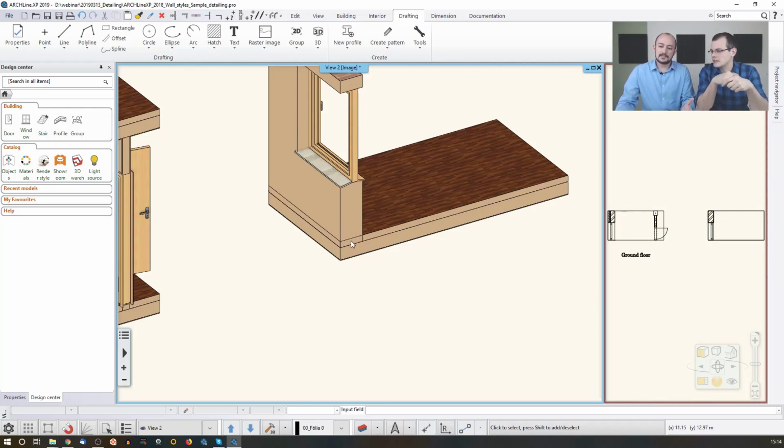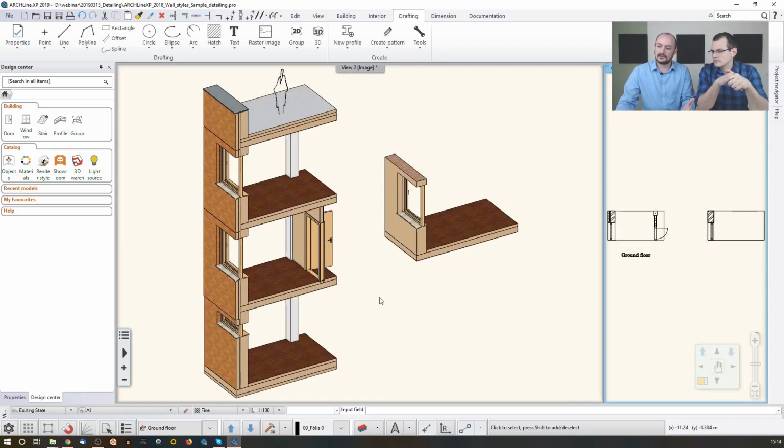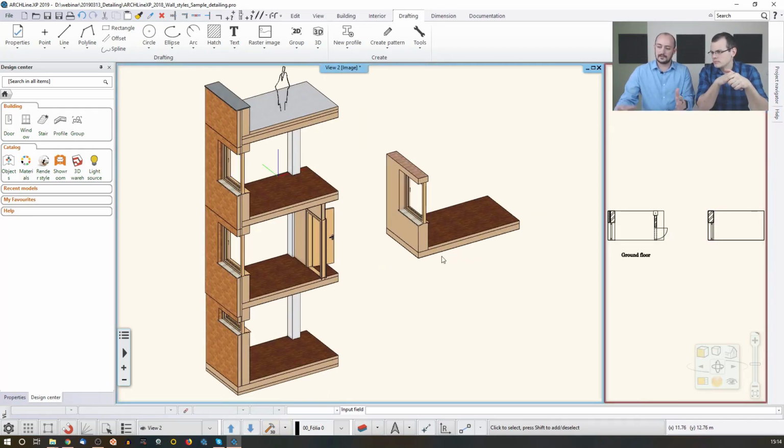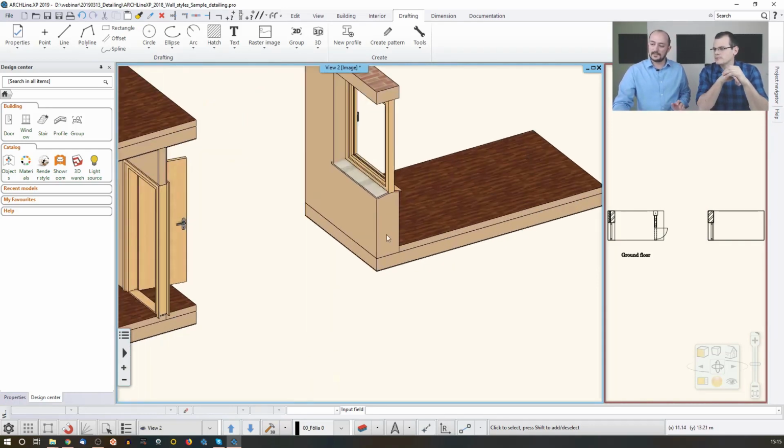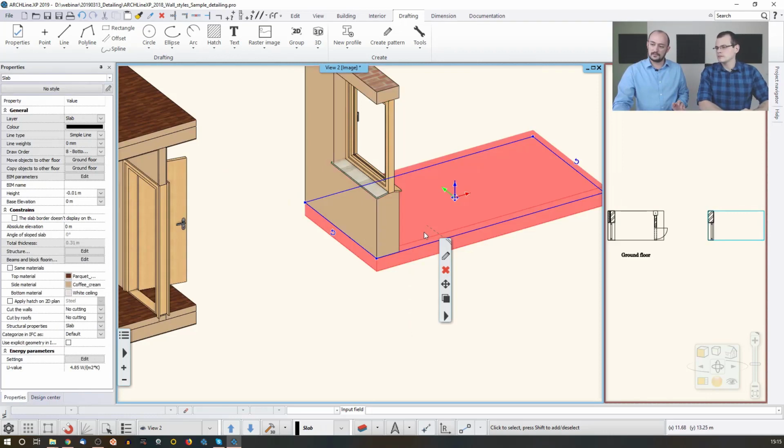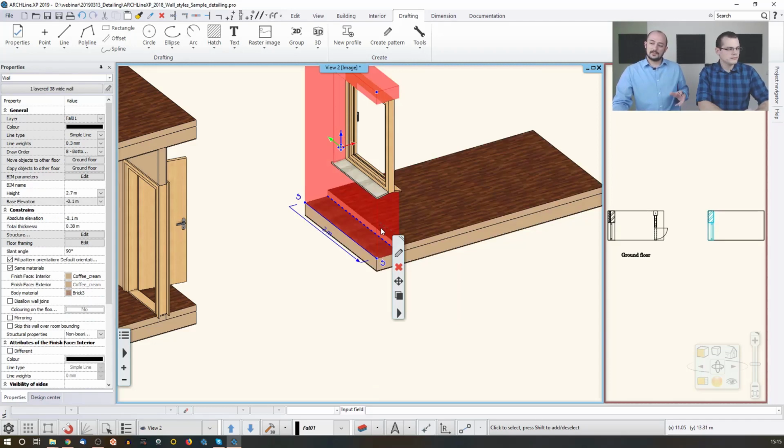Well, this is only a matter of rebuilding the 3D. When I rebuild the 3D, the connections become correct. They were just overlapping temporarily. But now they are occupying their own space, and they are proper, and the layer is where it should be. So this way you can set up the starting point of the level, either by literally typing the value or by binding it to a value of the level.